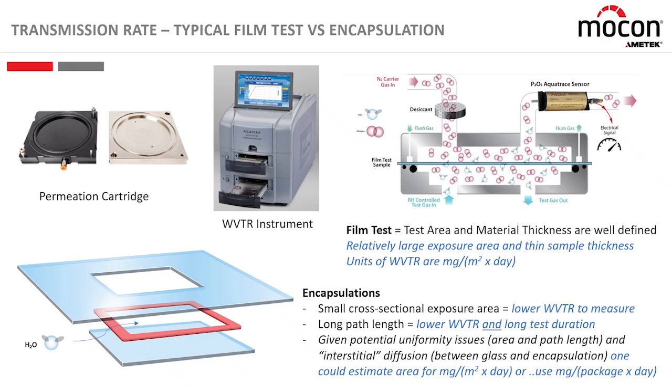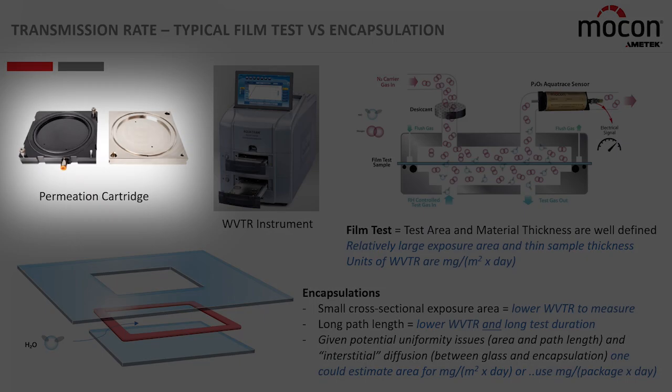We mount it on top of this diffusion cell cartridge. This other cartridge clamps in place, goes on top of it, and sandwiches the material in between. On the bottom side, we can put a controlled humidity, 90% RH, 75% RH, or we could even put a little wet sponge down here. On the other side of the material, when this is all clamped together, we'll have dry gas sweeping.